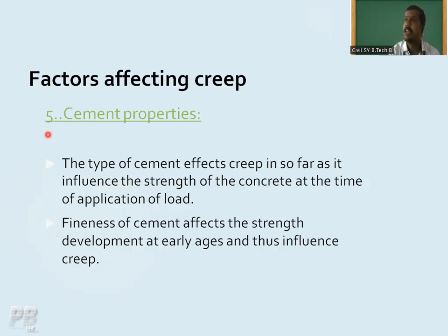For OPC, the fineness of cement should not be more than 10%, and for PPC, it should not be more than 5%. How do you have to find out the fineness of cement? For that, you have used a 90 micron sieve, correct? And you have done the sieve analysis. Have you done this practical? We have done it, definitely. The first practical that we have taken. Okay. We have determined the fineness of the cement. Okay. Hope you have understood this now.